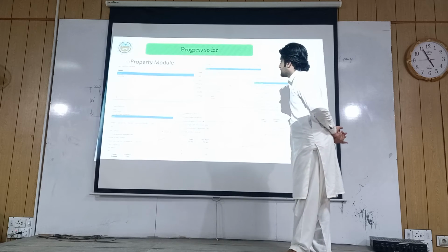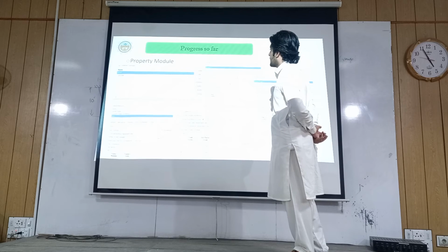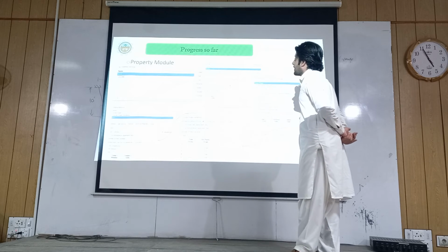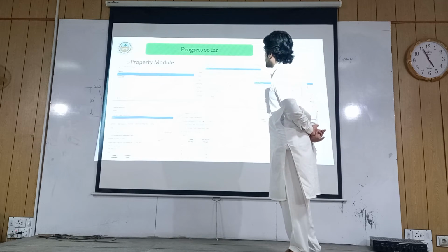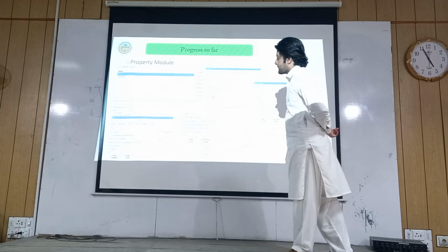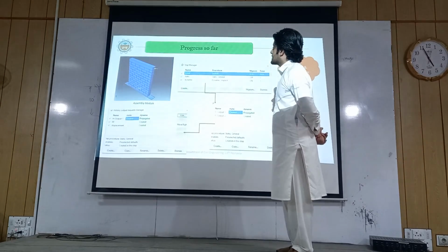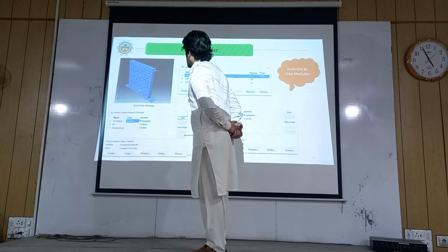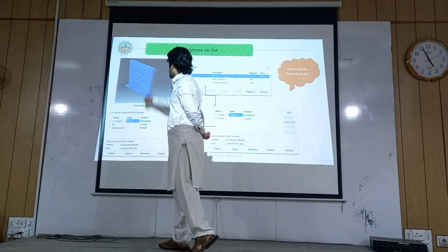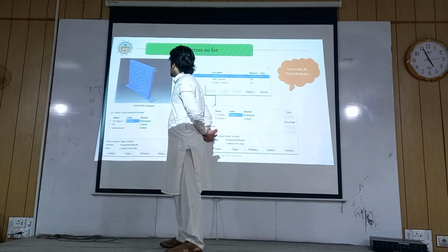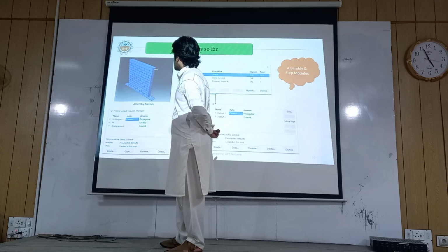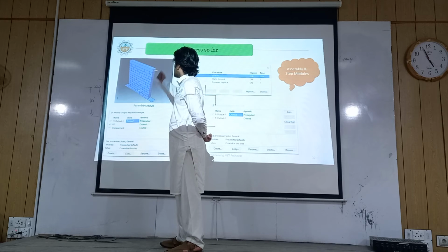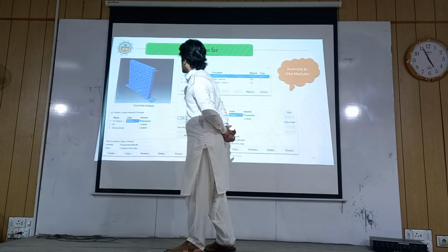In the brick properties, we have defined density, the brick values, the brick hardening values, and the elastic values for bricks. In the step, we have assembled the elements in this way, and we have defined different reference points. The first one is where we will apply the dynamic load, and the second is where we will get all the reactions. Also, we will get the displacement and the forces here, the reaction after analysis.